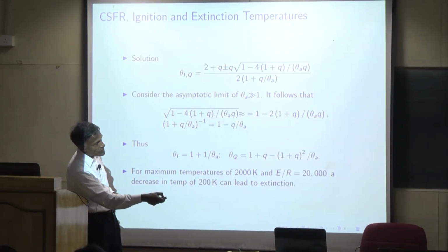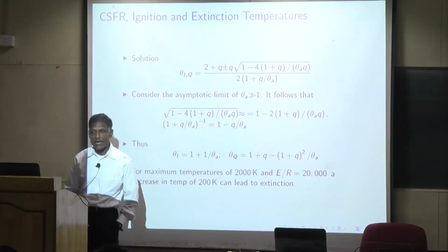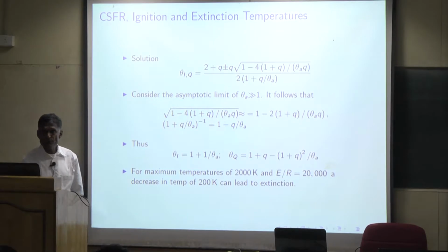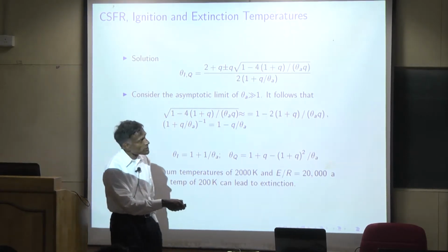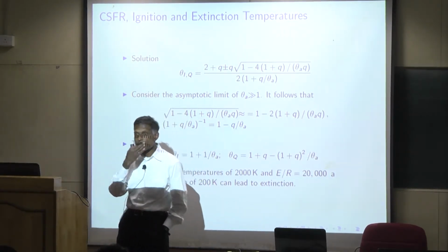And then on the other side, if you have a steadily operating reactor, by increasing the flow rate, there's a small drop in temperature, and then again discontinuously, the reactor extinguishes. So this particular behavior is only possible for large activation energy.